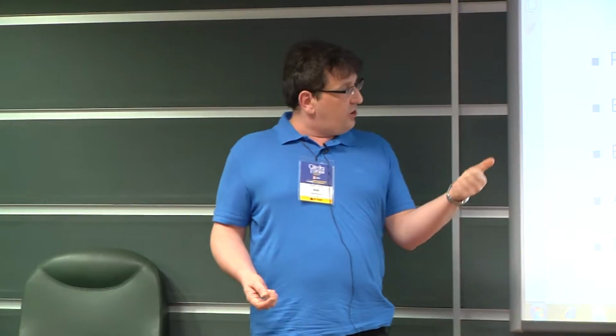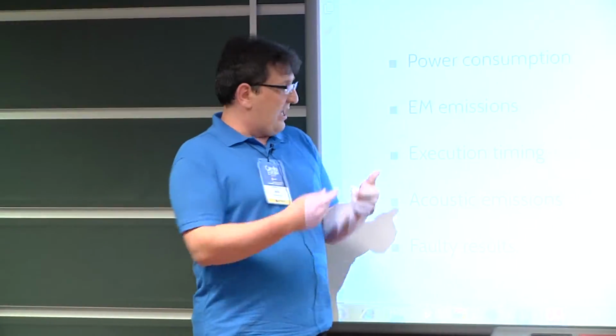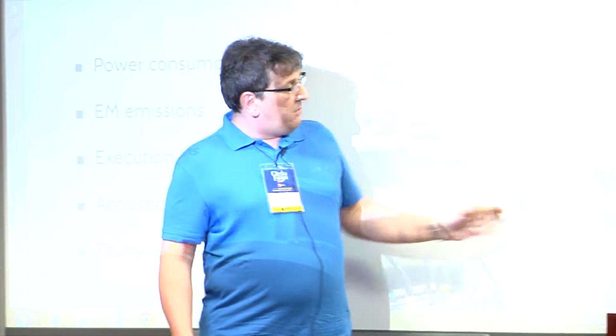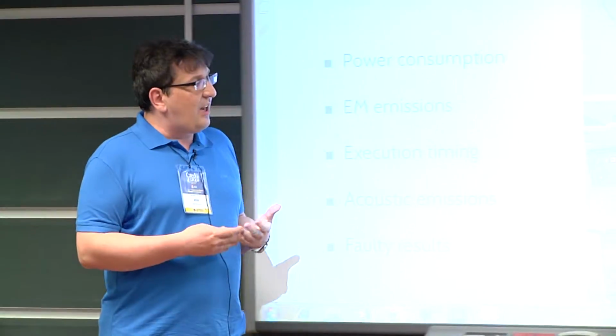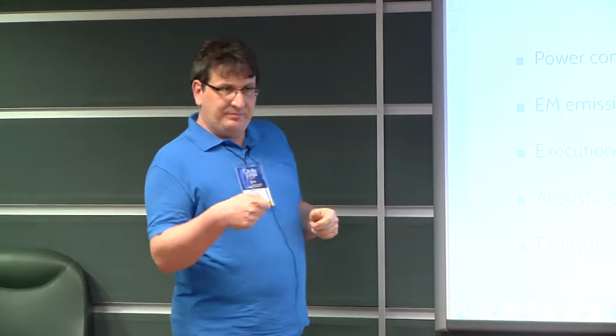You can measure the behavior of your application, measuring the timing of every run, acoustic emissions or faulty results. When you have an embedded device in a low-cost, low-budget laboratory, you can easily measure the power consumption or the electromagnetic emission of every embedded device.